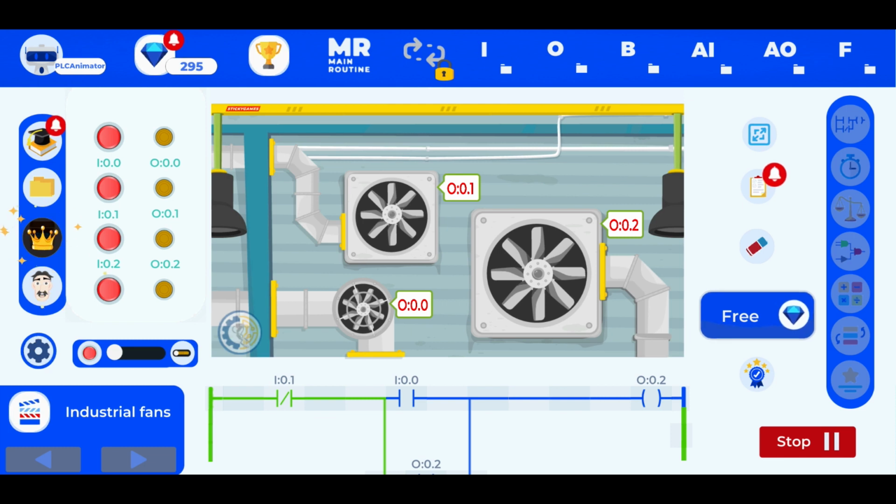Now here, I'm not going to press anything because I wish to demonstrate. If you see here, our flow is always going to happen. My line is always going to indicate that there's something here. So if I press it, it's going to stop. Okay? So when I press this, that contact is going to open. So if it does open, it's not going to allow for my signal.